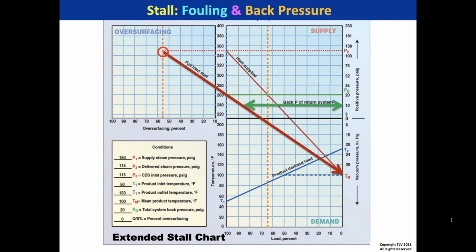Now, the first thing we want to notice with our steam pressure profiles is that we've got a lot of area in that heat exchanger when it's new. So our steam pressure can actually drop down to 20 psig if you read off the right-hand scale to the right of the red circle. Our steam pressure is 20 psig at 100% of load.